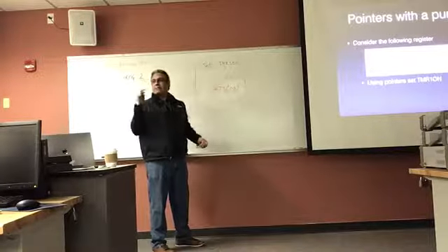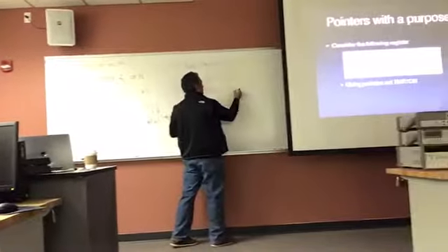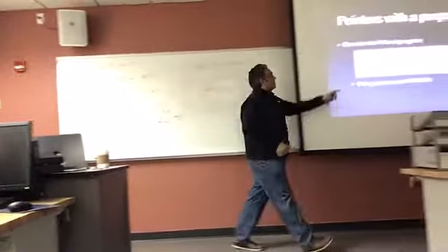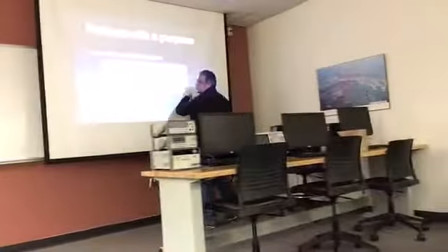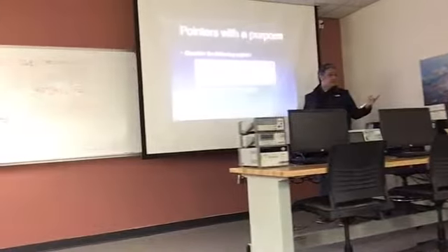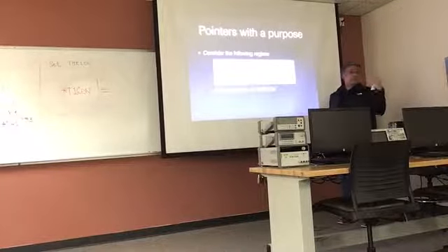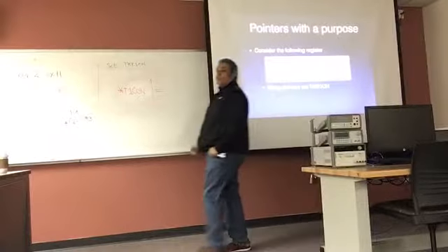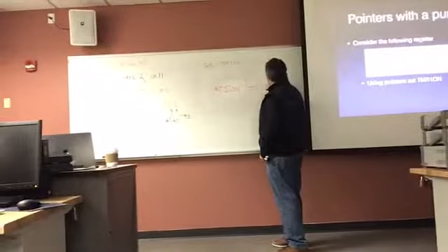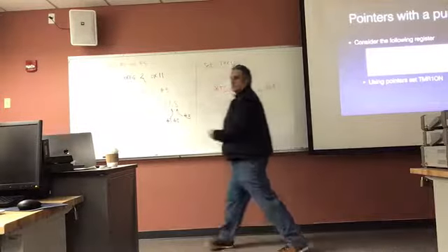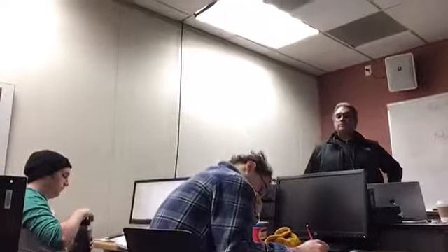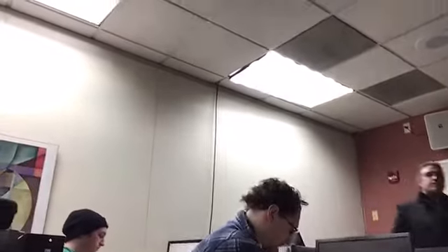Then I want to save. So you go, save it. What's the position? TMR1 on is located in bit what? Bit 0. It's on bit 0. And then the number for bit 0, I already know. That's hex 1. Because that's the position of bit 0 according to the table. Right? Make sense?